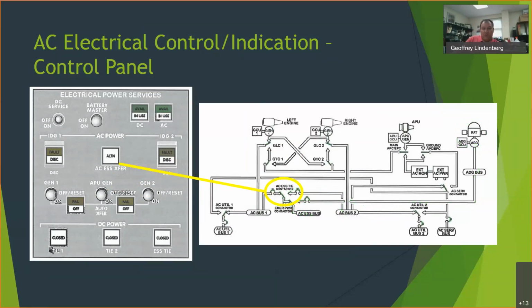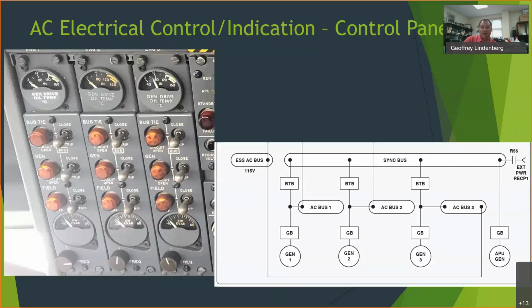The power control on our parallel bus system is this panel that I discussed earlier. And so here is, again, a schematic layout. So here's that bus tie, that sync bus. Sync bus or tie bus are kind of interchangeable names, so you can see that here. And we have our AC buses shown, right? We've got the little rectangles that show the buses, I mentioned this. And then the bus tie breakers are the switches you use to power them.